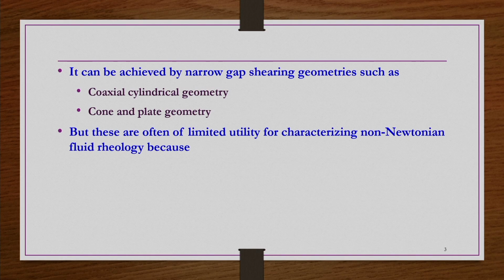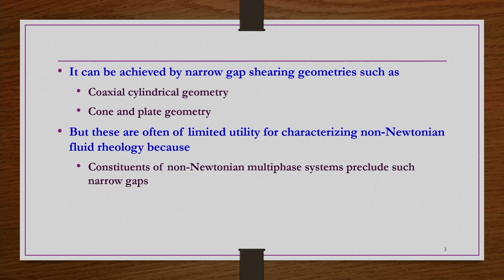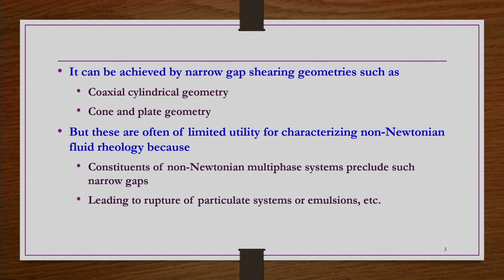But the problem is that these are often of limited utility for characterizing non-Newtonian fluids, because, as mentioned, the constituents of non-Newtonian multiphase systems preclude such narrow gaps, leading to rupture of particulate systems or emulsions, etc. So, even though narrow gap shearing geometries are theoretically good for a reliable measurement of rheology, because of problems like rupture of particulate systems or emulsions, the non-Newtonian multiphase system precludes the use of such narrow gaps.